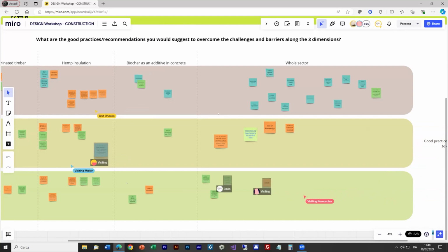This is the best case scenario. But if remanufacturing needs to happen, then it needs to be kept ideally to a bare minimum. There are a series of strategies, technically speaking, which can be put in place in order to do that. One of the ones we use is to always make the connections of our buildings accessible, use dry construction rather than wet construction anywhere, and think about what the scenario is for the reuse of components, because this is the biggest deal. Having a sort of financial case for that is what we find to be a bit difficult yet, but it's something which even as architects we try to think of when we work on our buildings.